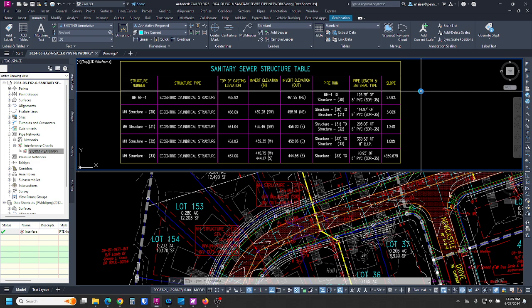We also have lateral design tables, which I don't have a sample file ready today to go through, but we could do that another day. Those usually go on the plan and profile sheets for the plans for the sewer authorities, and show all the Y inverts, end lateral elevations, lateral lengths. That's where you type in your end lateral GPS coordinates on your as-built, all that good stuff.